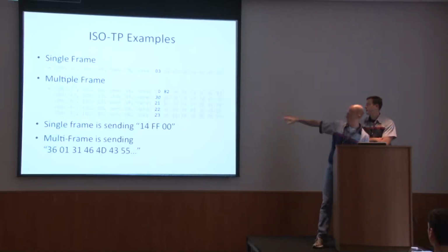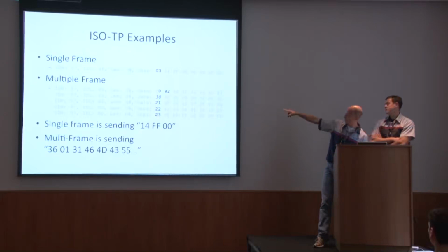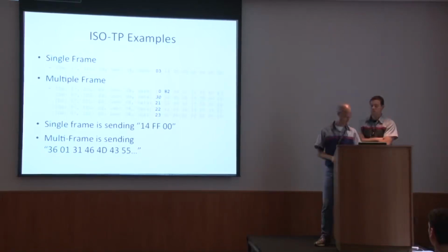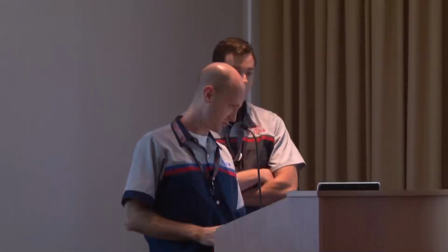What if you want to send a lot? In this other example, there's the 1 that shows that this is going to be the first of many messages to expect. And then the length is 082, so expect 82 hex bytes altogether. And then the data starts.